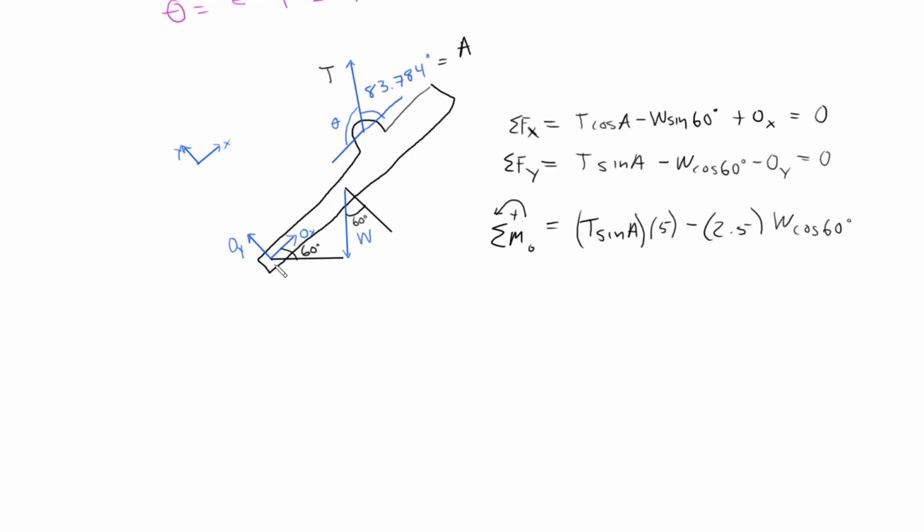These forces are not included because there are no perpendicular distances of OX or OY to the pivot O. Since this problem is only asking to solve for the moment about O, we could solve this equation. It does not equal 0 for this case, or actually it might if we include a reaction force pointing in this direction, but since this is a pivot, it is free to rotate, so there is actually no reaction force. So this moment cannot equal 0 in this problem.